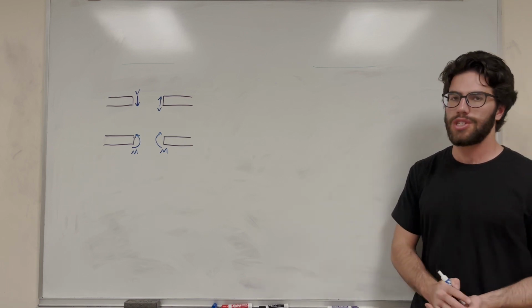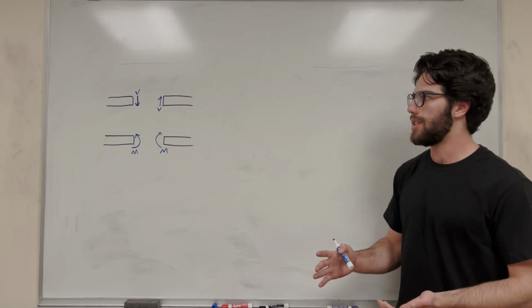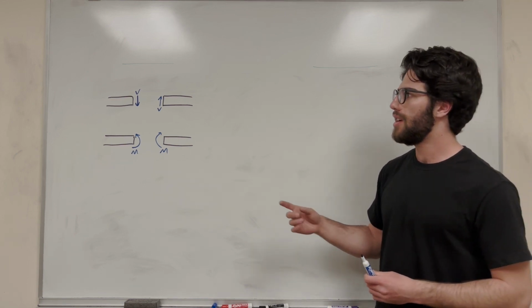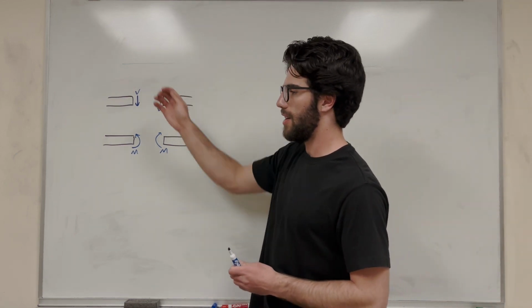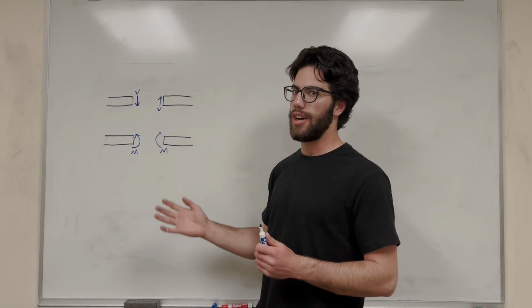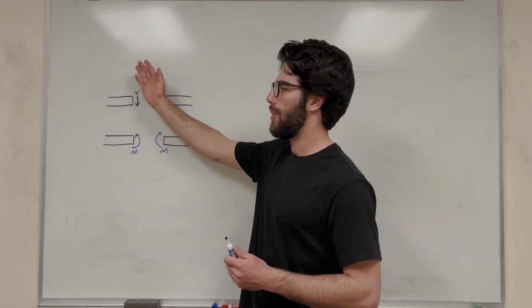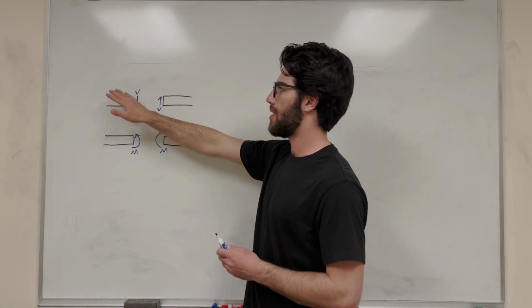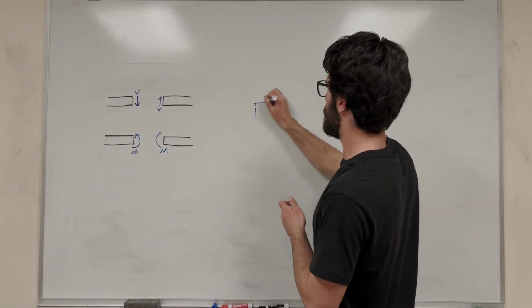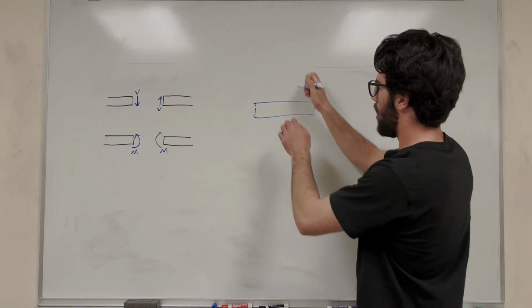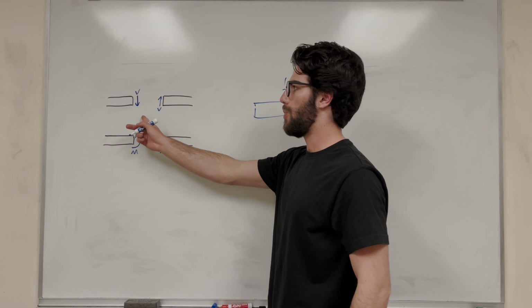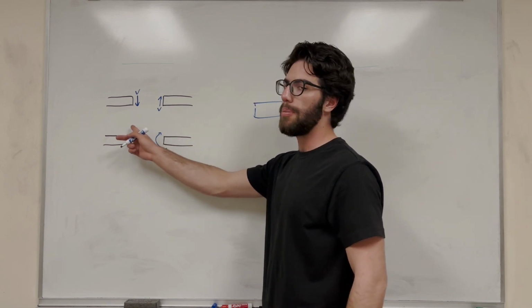And so really quick, before we start jumping into the problems where I'm going to explain it more to you, I like to remember the convention for shear and moment. When we're taking shear and moment, we're going to take a cut on the beam. If we take a cut and we cut off all of the right side, say we're looking at a beam that's like this, and we cut off here and cut everything over here, the shear is going to be pointing downward and the moment is going to be curled upward.